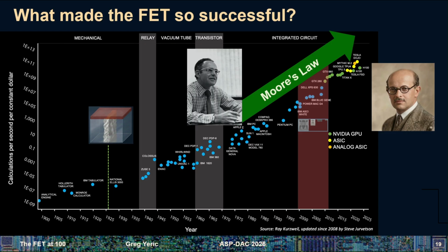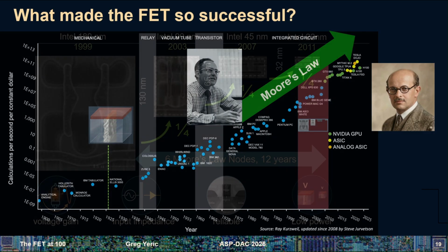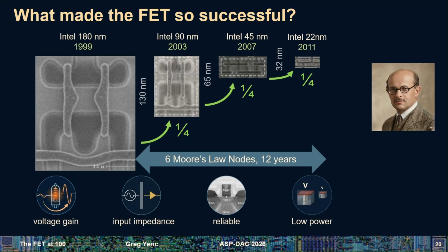When you zoom out this far, it's hard to really appreciate it. But if I just take the time in this red band here, that encompasses actually 6 different Moore's Law nodes, because I'm skipping, in the pictures, the nodes that are in the vertical text here. So 180, 130 to 90, and so on. So each time I skip a node, I'm doing a 1/4 area, because Moore's Law is 1/2 the area every node.